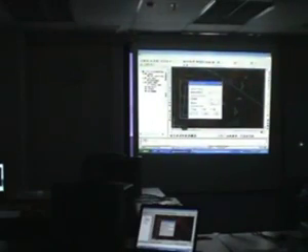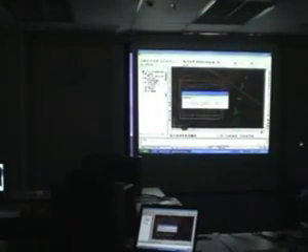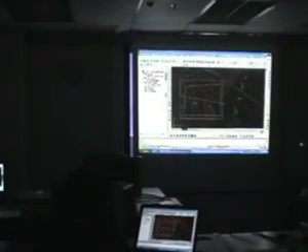You have to take into account that whatever soil you import is not necessarily how much is used to fill. You have to take into account the compaction and the settling. So let's say it's 20%. I'm going to put 1.2. Of course, you can always adjust that later. I'm just going to call this grid. Say okay, and the volume calculations appear at the bottom.